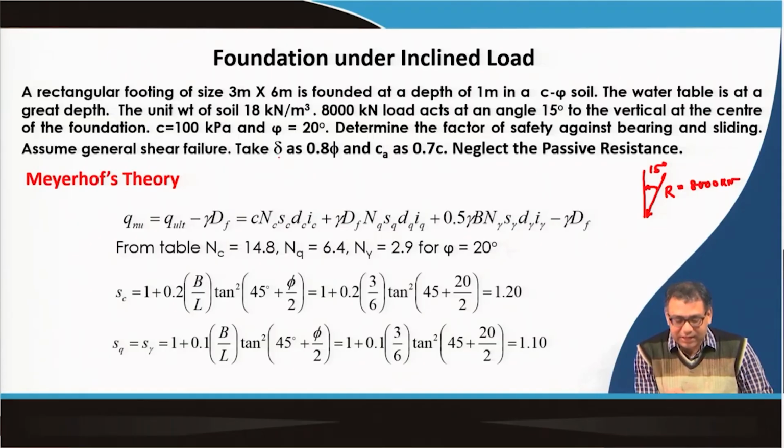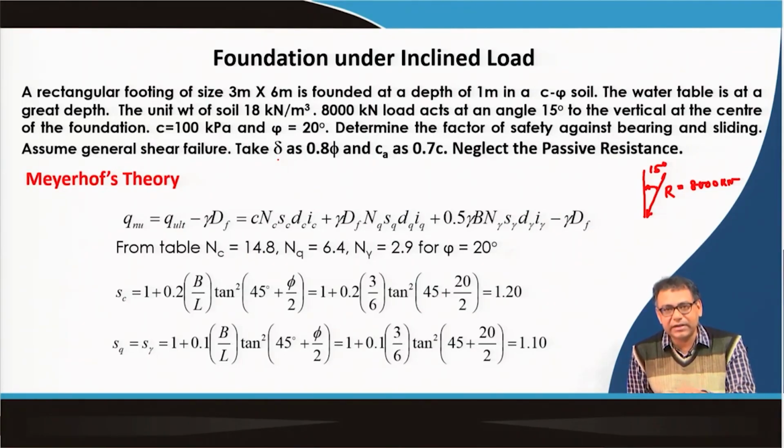That is why this delta, because this delta is the friction angle between the foundation and the base soil, and this adhesion is the adhesion between the foundation and the base soil. Remember that this is the base soil, and you have to neglect the passive resistance.